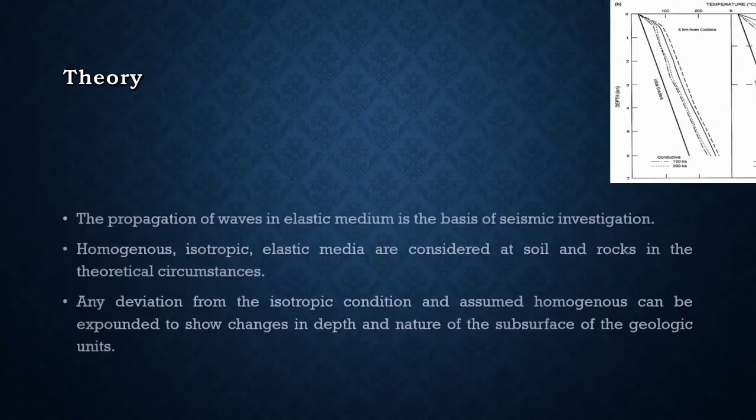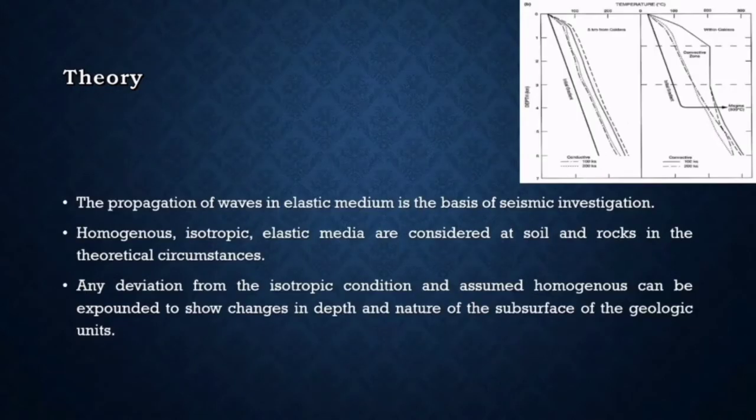Theory. The propagation of waves in an elastic medium is the basis of seismic investigation. Homogeneous, isotropic, elastic media are considered as soil and rocks in the theoretical circumstances. Any deviation from the isotropic and assumed homogeneous condition can be interpreted to show changes in depth and nature of the subsurface geologic units.